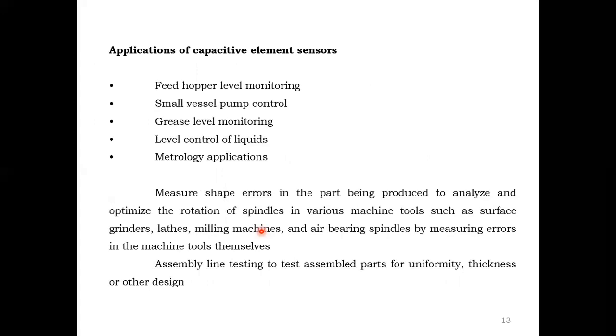Monitoring, level control of liquids, metrology applications. Measure shape errors in the part being produced to analyze and optimize the rotation of spindles in various machine tools such as surface grinders, lathes, milling machines, and air bearing spindles, by measuring errors in the machine tools themselves. Assembly line testing to test assembled parts for uniform thickness or other designs. Like that we can use the capacitance sensor.